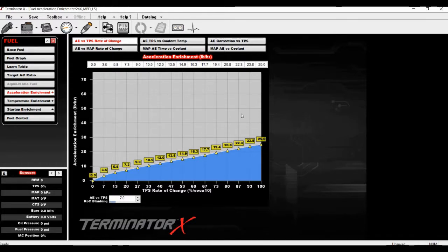This is because whenever you just zing the engine, say you're in neutral and revving up the motor, what happens? The engine can't change fast enough. The ECU can't keep up with what the engine is doing fast enough. So the easiest way to explain that is, there's a moment in time where the manifold still reads the lower pressure but is on its way to the higher pressure. And since that is a reactive type measurement, not a predictive one, we need to adjust to a predictive style of measurement where we see the TPS rate of change and know I need to add some fuel here.